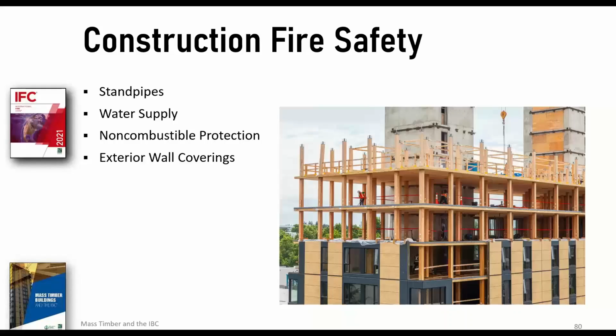But mass timber inherently, because of the way it's built, has less of a chance of a construction fire than other types of construction, because to put it in context of something you're probably familiar with, it's most like precast concrete construction.